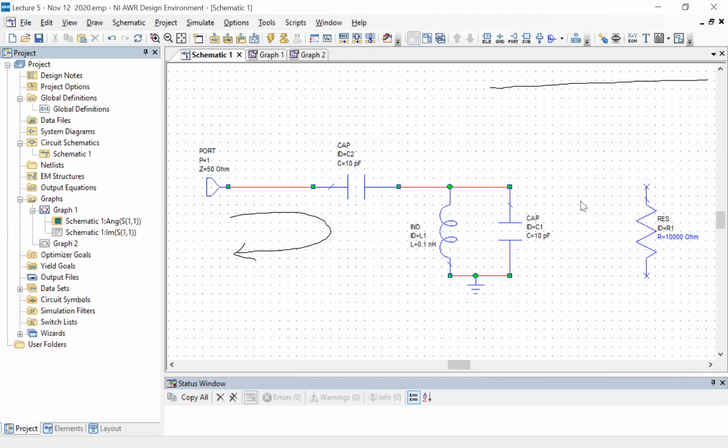We do not want the resonator or any other circuit we introduce to absorb any energy on its own. That is the sort of underlying constraint or premise we are starting with for all of these discussions. Okay, so we cannot add a resistor. Resistors are bad in general, in anything we do in our lab. But here, that is the underlying reason why, is that we basically want all the signals going in to come back out.